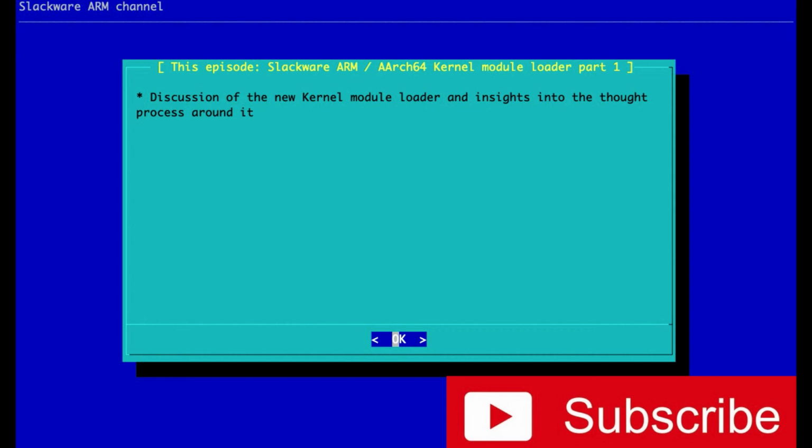The way people have always flashed U-Boot from an SD card image is that you create a FAT file system and put a U-Boot script file, in the U-Boot scripting language, there. That runs the U-Boot commands that you've used before, the flash management commands from the U-Boot console, from script, and then it just runs. Then it uses the U-Boot LED functionality to blink the LEDs on the board, from the script. So that's what they do.